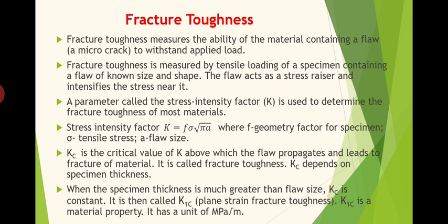When the specimen thickness is much greater than the flaw size, Kc is constant. It is then called K1C, the plane strain fracture toughness. K1C is a material property. It has a unit of megapascal root meter, or megapascal into meter raised to 1 by 2.